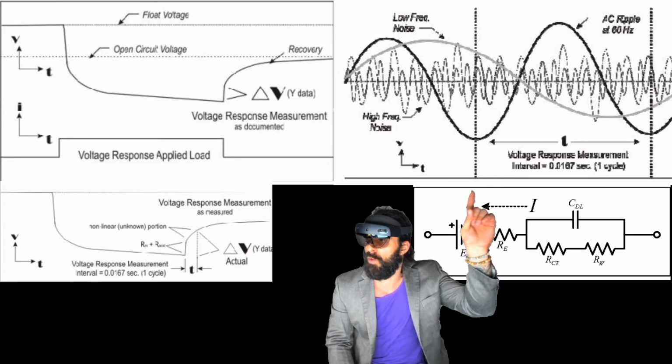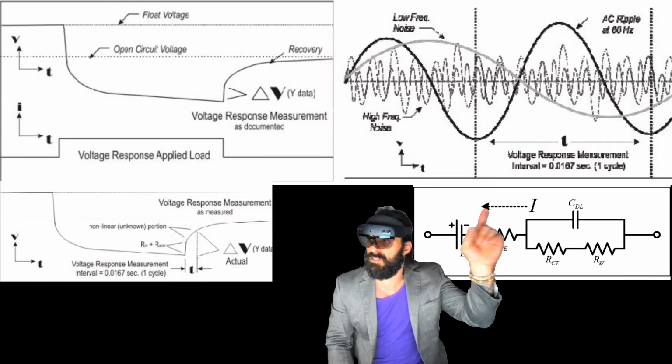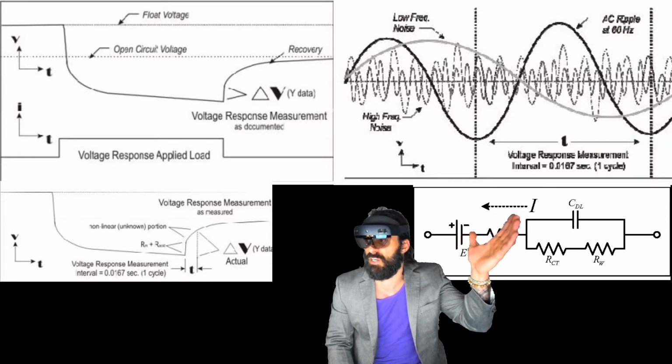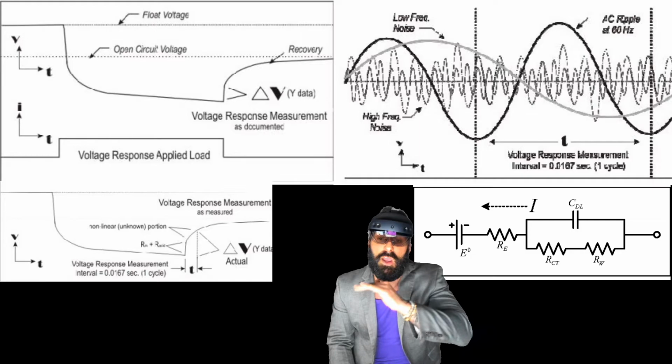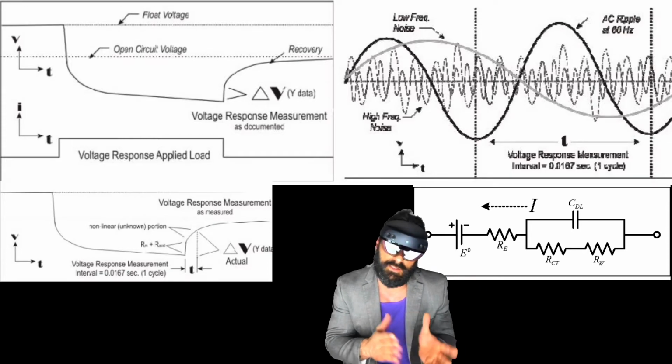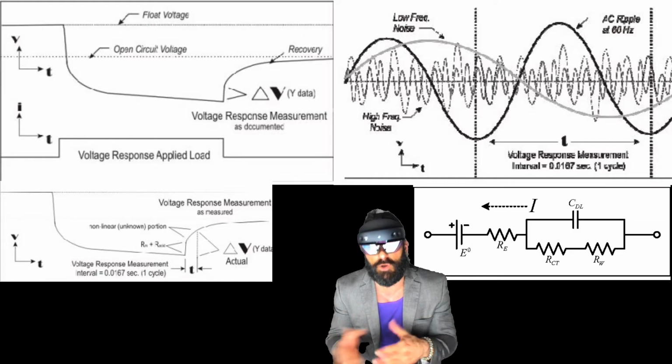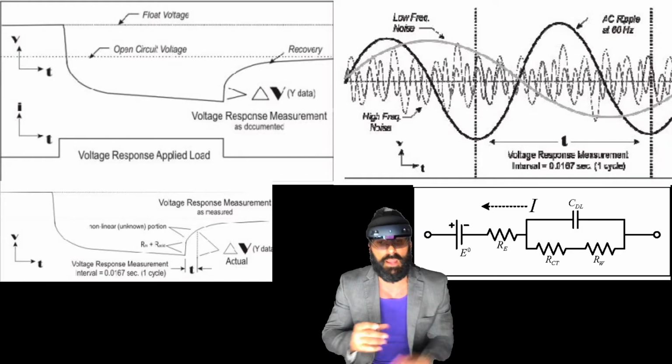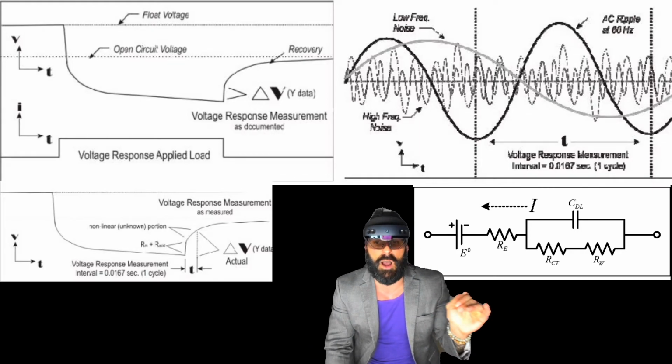So if you look all the way up here, look at all that noise riding on the signal. I see this even on DC buses constantly, and we'll get into this when we review insulated gate bipolar transistors, IGBTs, and silicon-controlled rectifiers, essentially the charging mechanisms on inverters and big power systems. AC-based methodologies depend on the injection source.